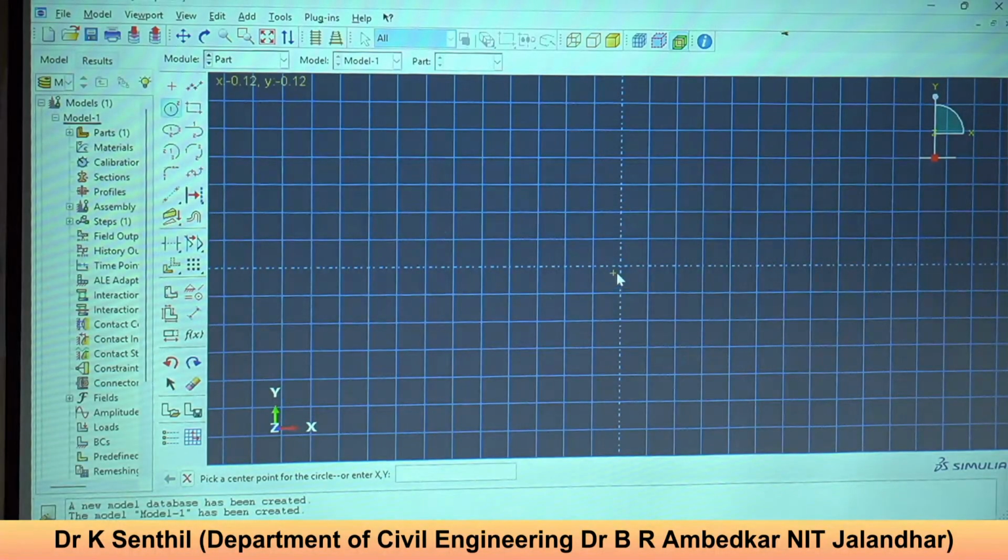You can take a circular pile at 0, 0 and minus 0.5, 0.5. Sorry, it's 0.25. We kept minus 0.5, right? So that means we kept a 1 meter diameter borehole. Okay, sorry, that should be 0.25.